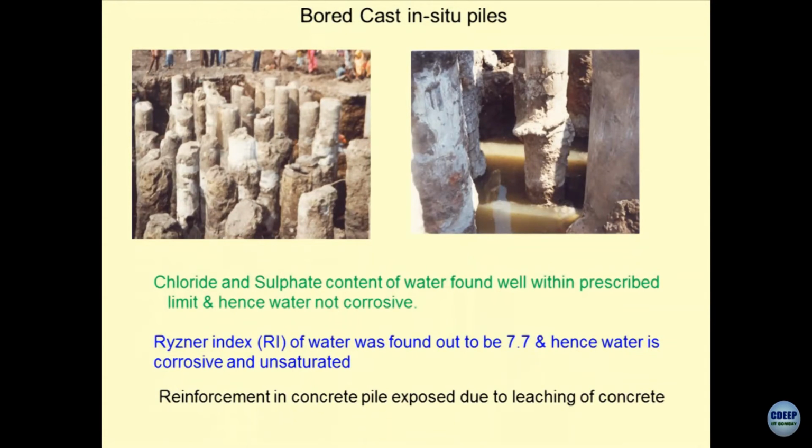And why? What is the reason for this, which has been ignored? Look at this, you designed a pile for certain dimensions and capacities. So, what has happened here? What does this portion tell you? The concrete has got corroded completely. What is the cover of the concrete which you put on the reinforcement? 15-20 mm. I hope you can guess from here what would have happened to the reinforcement itself. If you check on the net, you will find it's an eye opener that this type of ignorance which was prevailing in the subject has been overcome now, and people are designing systems which are more environmentally safe and compliant.